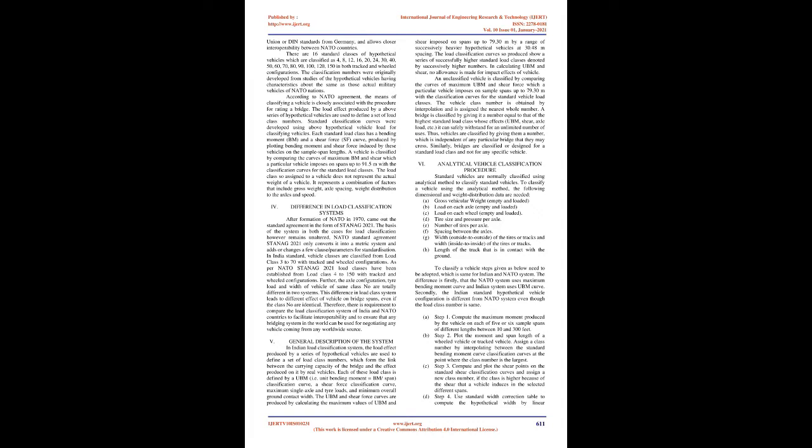Under this agreement, every bridge can be assigned a specific load capacity classifying number, a load class, and every vehicle is assigned to a specific category from a total of 16 hypothetical load classes. If the vehicle load class is lower than or equal to the bridge load class, that vehicle can safely pass over that bridge, else the vehicle will be diverted.